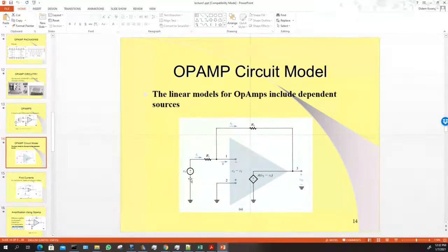You apply a voltage to this one, V1, and then you could apply another voltage to V2, and this will not pick up any current. The current that comes in here is almost zero. The way it's designed is to make sure that this op-amp, theoretically here, you can't see it, there's a blue triangle like this, should not take any energy, or just a minimal amount of energy from V1 and V2. At the output, it will generate A times V2 minus V1.